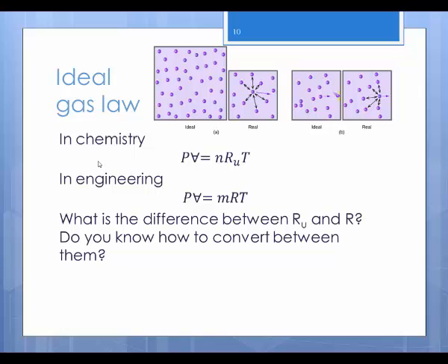Moving on from bulk modulus is trying to understand the ideal gas law and why it matters for what we're doing here. This seems like a chemistry concept, but in a lot of things in fluids and thermodynamics and related fields, it's actually really relevant. One important thing to realize that you may not have seen in too many courses is that pressure times volume equals the moles of substance times a universal gas constant times the temperature. This temperature is always absolute temperature, and this pressure is always absolute pressure.